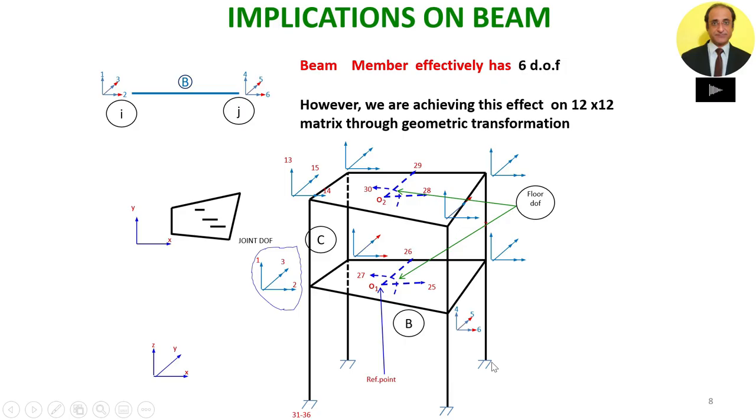IS 456 gives flexibility to the designer that he has the option of considering either the torsional constant J as 0 or a finite value. If the torsional constant J is considered 0, then the beams will not have any compatibility torsion, but if the value of the torsional constant has been considered, then the analysis output will show torsion in the beams.